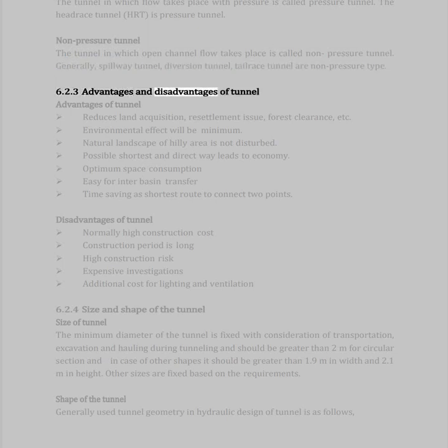6.2.3 Advantages and disadvantages of tunnel. Advantages of tunnel: reduces land acquisition, resettlement issue, forest clearance, etc. Environmental effect will be minimum. Natural landscape of hilly area is not disturbed. Possible shortest and direct way leads to economy. Optimum space consumption. Easy for inter-basin transfer. Time saving is shortest route to connect 2 points.